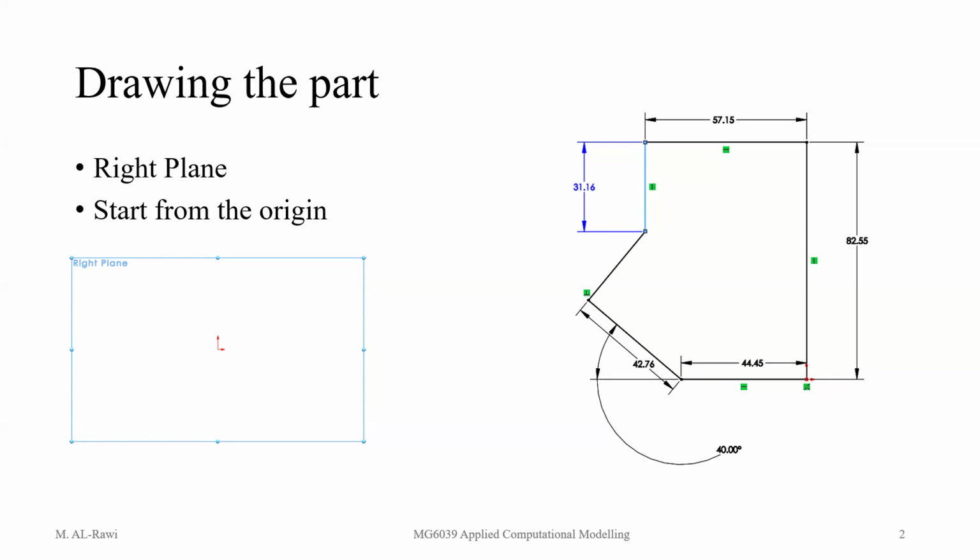So that should be 40. So if you do the entire angle, it should be 40 plus 180. So if it's not 40 plus 180, then it means that is not the right distance. So you can type equals 40 plus 180, because the dimension can accept equations. After drawing this line, can I give the angle? Yes, now you give the angle.